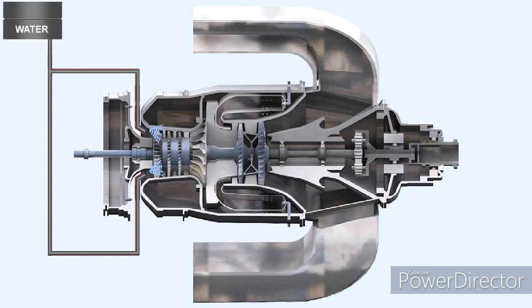Some centrifugal compressor engines, and also some small American-designed axial flow compressor engines, used a system of injecting the water into the engine intake. Unfortunately, the water distribution was not of the best, and also the quantity of water injected had to be limited, so as not to cause an engine flameout.